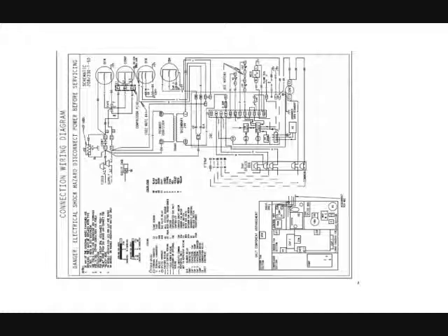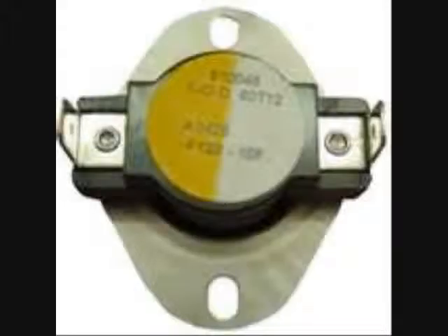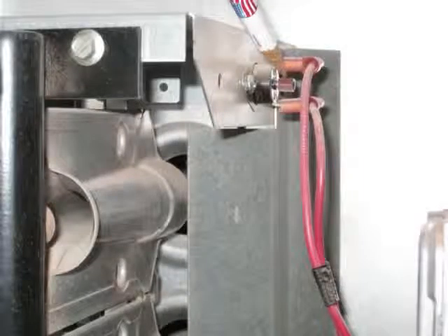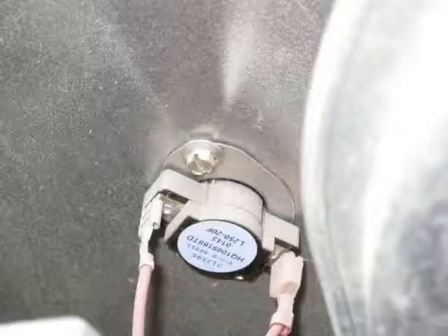While your burner is going, you have several sensors which protect your unit from overheating. Rollout sensor. Called this because it is supposed to sense flames which are rolling out from where they are supposed to be. These can be located at the burner, on the blower housing, and on the flue pipe itself. High limit. This sensor just breaks circuit when it gets too hot.